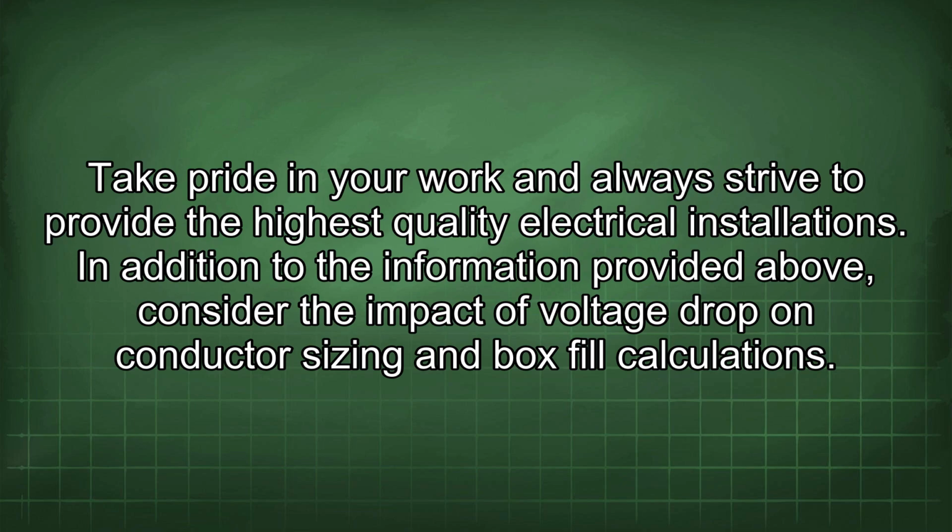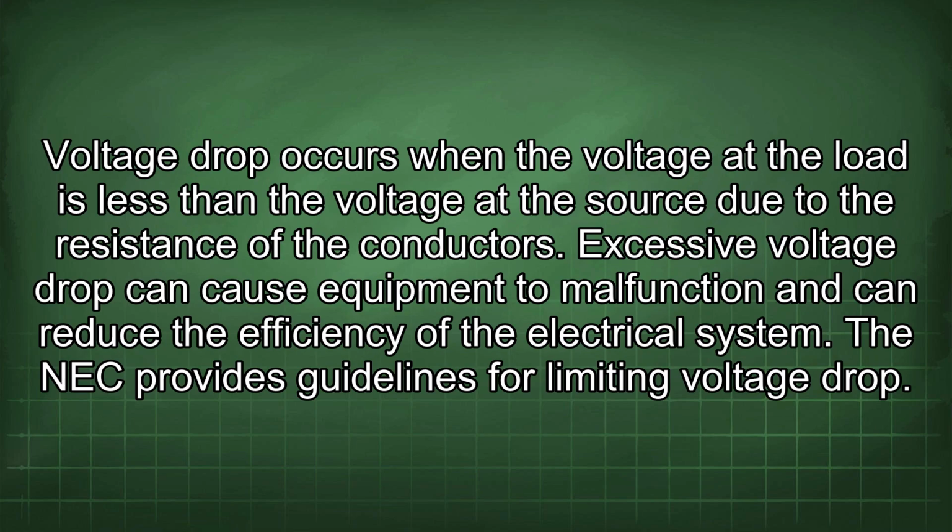In addition to the information provided above, consider the impact of voltage drop on conductor sizing and box fill calculations. Voltage drop occurs when the voltage at the load is less than the voltage at the source due to the resistance of the conductors. Excessive voltage drop can cause equipment to malfunction and can reduce the efficiency of the electrical system. The NEC provides guidelines for limiting voltage drop.